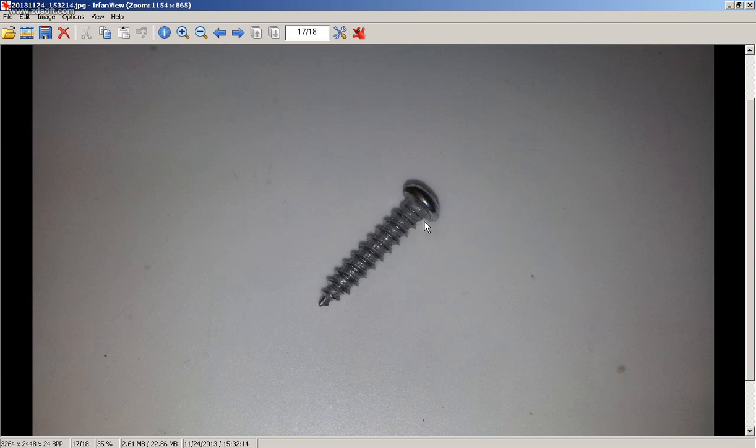I have already measured the dimensions of the screw. The length of this thread area, not including the head, is 19 millimeter. And if you look, we have a screw thread here. It's a V-shaped thread, and the size of the V is 0.8. And we have a number of revolutions here: 1, 2, 3, 4, 5, 6, 7, 8, 9, 10, 11, until at the end here we have 12 revolutions.